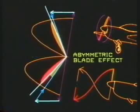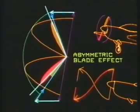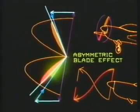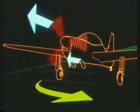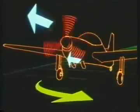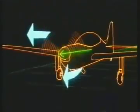Now the downgoing blade has to cover a greater distance than the upgoing blade in the same time, so its relative airflow is faster. Similarly, the angle of attack of the downgoing blade is greater than that of the upgoing blade. Therefore, the downgoing half of the propeller will be generating more thrust than the upgoing half, which will tend to yaw the aircraft to port until the tail wheel is raised and the propeller's axis of rotation is brought into line with the aircraft's horizontal path.